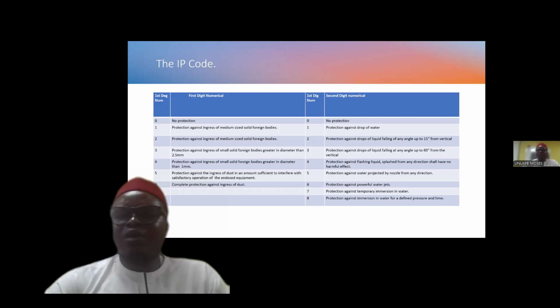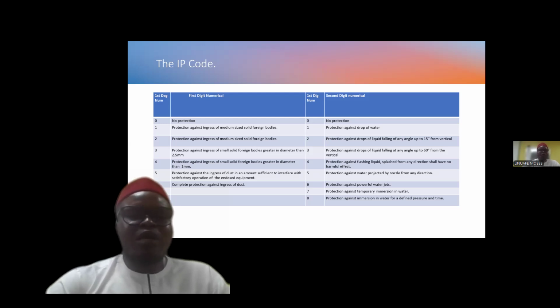While the explosive protection of pressurization, which is Ex p, relies on the seal of the enclosure to maintain a protective gas pressure. And furthermore, the explosive protection of intrinsic safety, which is represented by Ex i, may still require an IP-rated housing to protect the associated equipment.